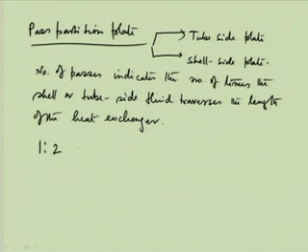We call it a 1:2 shell and tube heat exchanger. The common types are 1:4, then 2:4, and then 2:6. These are very common, and are called multi-pass heat exchangers.